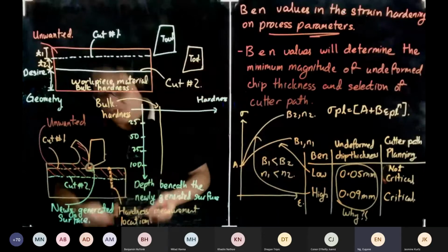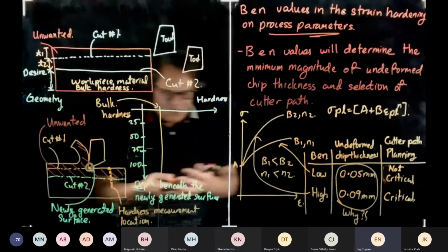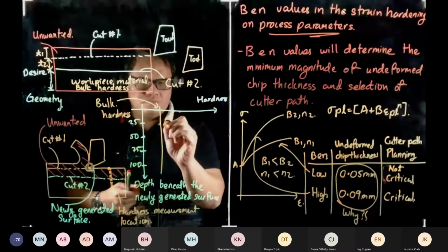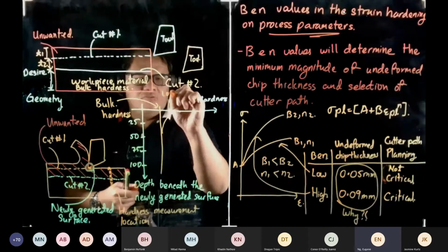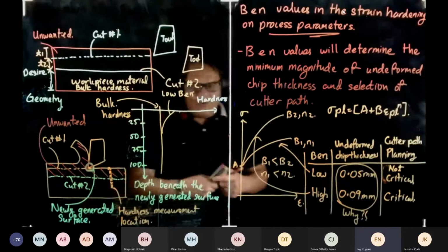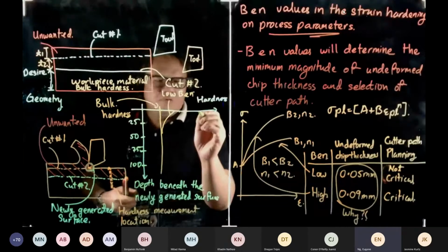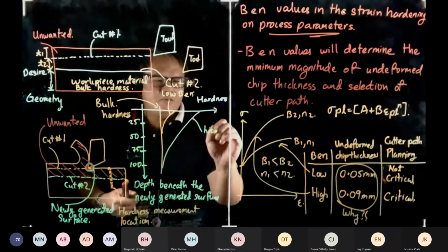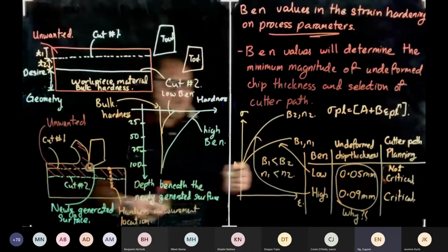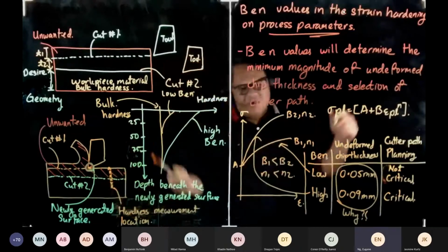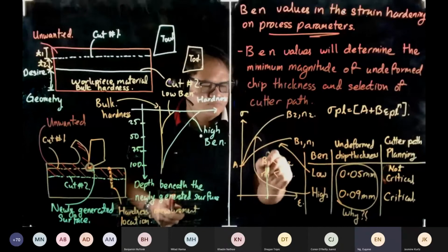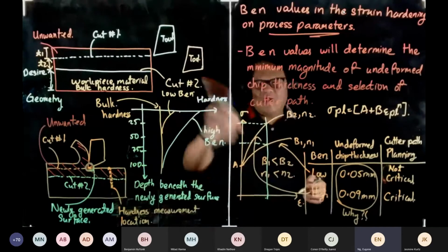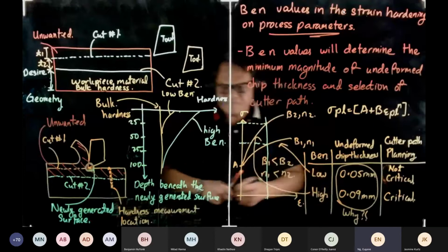So after machining, because of the heat, because of the BUE, we will have two trends. So the first trend over here, for this case, you have low BUE. But when your BUE is high, you have this. So over here, this is your high BUE. Why is it high? For example, if they fracture, down here if this is a fracture strain, you can see the high BUE. The stress is higher, and the hardness also is affected. So now, let's see what happened.